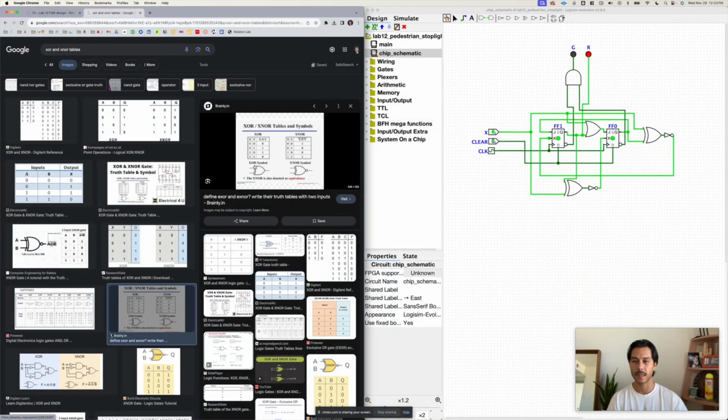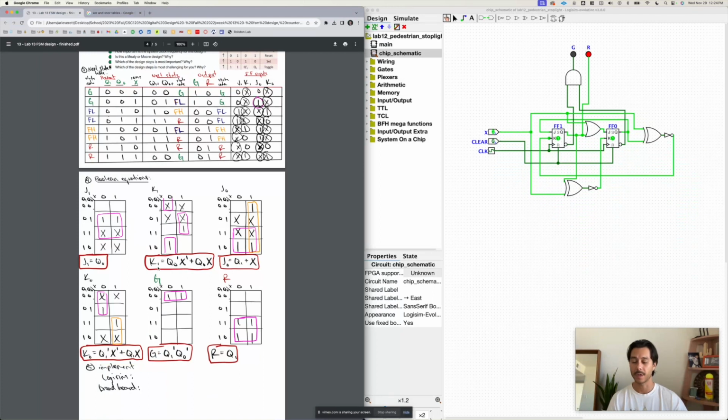up these patterns in that XOR is either-or. You can either have a cheeseburger or a chicken sandwich for dinner, but not both. And then XNOR is all or nothing. You either get dinner or you don't. And you can use these to simplify the K1 and K0 JK input equations down even further.